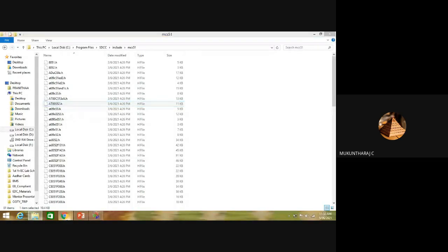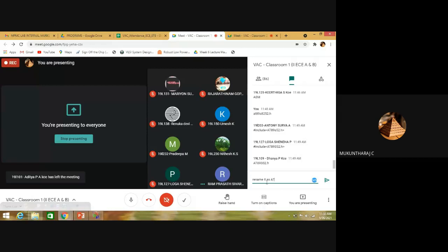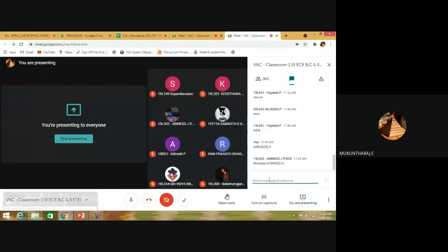What I typed in the chat box is going to be available with the SDCC software once you install. After that you have to rename it as AT89S52.h. You have to do this before you start your program. Otherwise, your program will show you an error. Clear about this point?